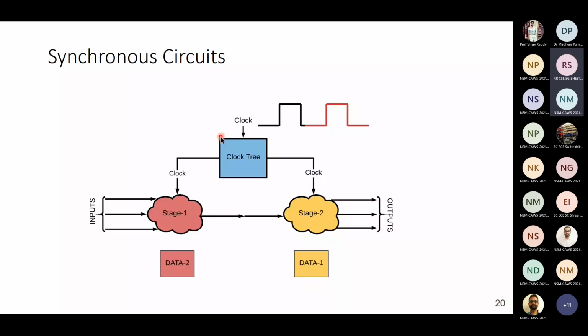And then if all the test benches are correct, you would go on to the next set where you would do rigorous testing and verification that the processor works fine. People use Formality or some other tool to check that all the cases are covered, and it is a completely verified system.